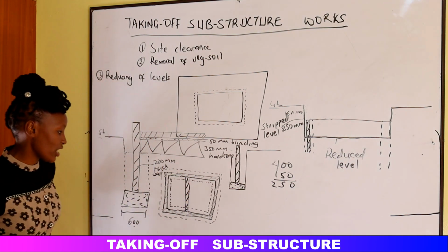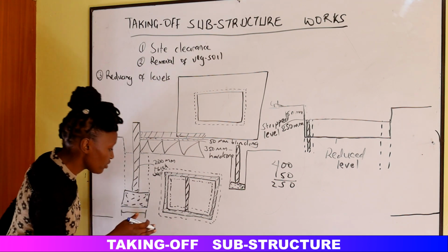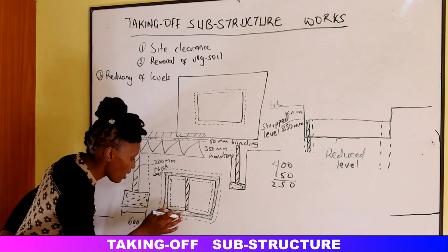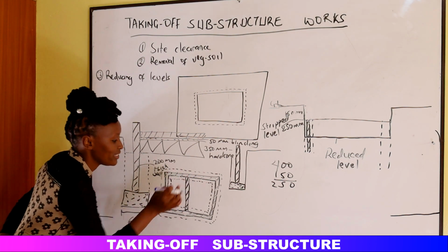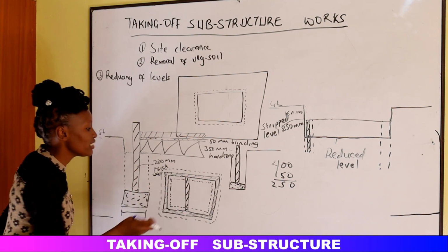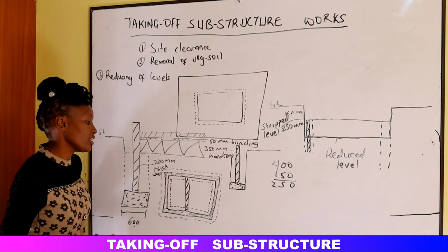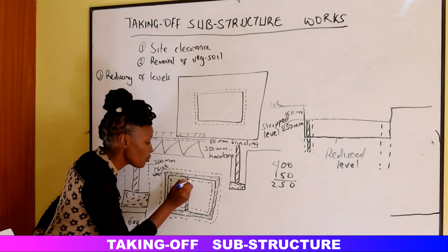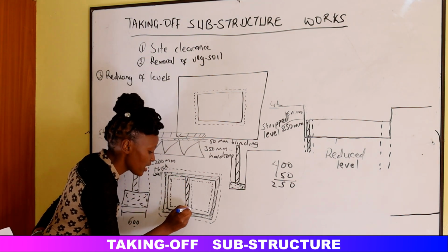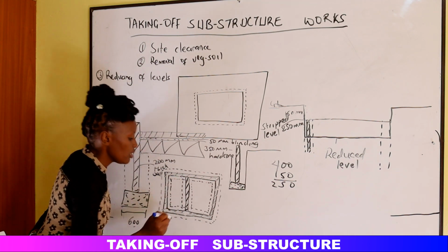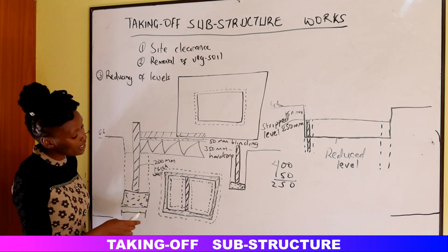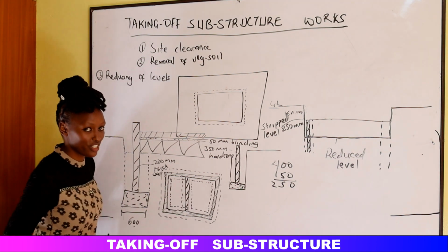How do we measure for the trench for the internal wall? You see, these walls were meeting, the external wall and the internal wall. They meet. And around this one we have a trench. Alright? You should always use the broken lines to show the trench.